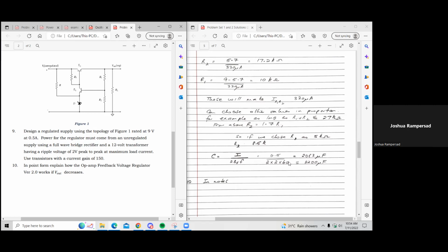I reached up to the op amp, and then after that I need to do that. The op amp design is actually fairly easy because you don't have the base of the transistor to consider in that particular design. You just really have to get the voltage divider, the sensing resistors, and the bias resistor for the Zener, and then the rest is there. You don't have too much more to do. It's a very nice, straightforward design, and fairly simple to work out in exams.